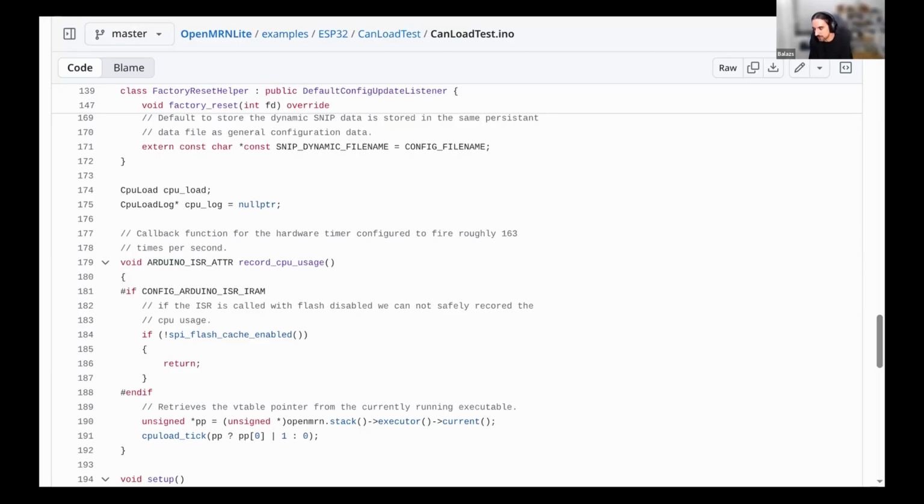So yeah, that actually does work. There are difficulties with it. If you are very careful and you are aware of these difficulties and you did your wiring properly, then it's going to be no problem. Of course, by the time you did your wiring properly, you actually have run 2 DCC buses, because you've run one for the actual track, which is after the short circuit detector of the DCC, like a PSX or whatever. And now you have another pair, which is before the short circuit detector. So now you actually did run another pair of wires in order to feed the ESP32s.